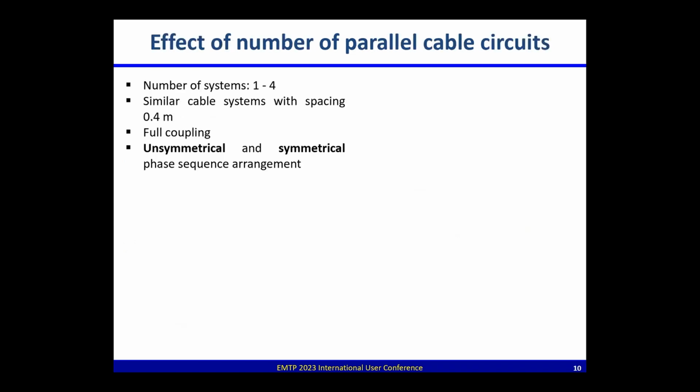Okay. So next we have examined the effect of the number of parallel cable circuits, to show that the inter-array cables that connect the wind park and the main grid are multiple. In most analyses, especially when a company asks a designer or a researcher to investigate the voltages and currents, typically they can say that okay, they are isolated, so more or less we can neglect their influence. Of course, this is also neglected in the technical brochures and the IEEE standard.